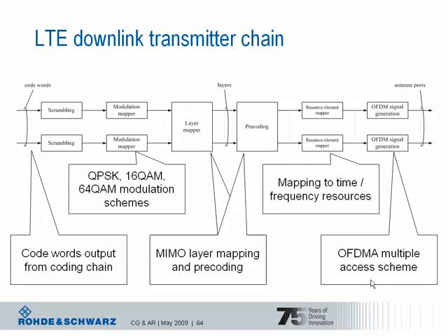You have different precoding types depending on the radio channel characteristics, for example. Then the resulting signal out of the MIMO precoder is mapped on the OFDM time frequency resources for transmission on each antenna port. And again, LTE supports up to 4 transmit antennas at the base stations. Could also be 2, for example, depending on whether it's 2x2 or 4x2 or 4x4 MIMO.